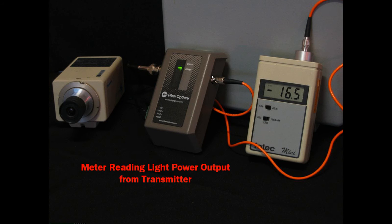So here you see we've got a fiber optic transmitter, and here we're reading the light power coming out of the transmitter, and you see we're reading -16.5 dBm. So fiber optic troubleshooting can be a very simple process. If you have a fiber optic link that you hooked up and it was working 3 months ago and now suddenly it's not working, the first place you go is to the transmitter. And you do what I'm doing right here on the screen. You plug your power meter into the transmitter with the transmitter powered up, and you say how much light power is the transmitter putting out.